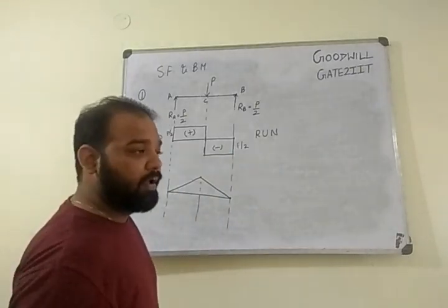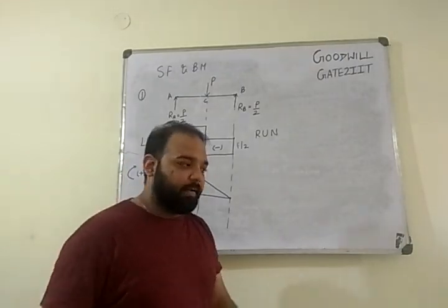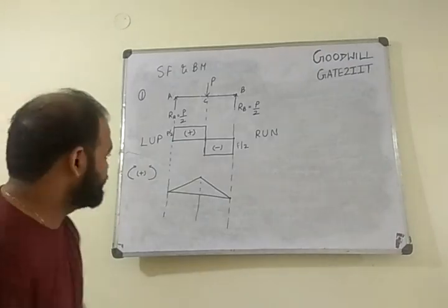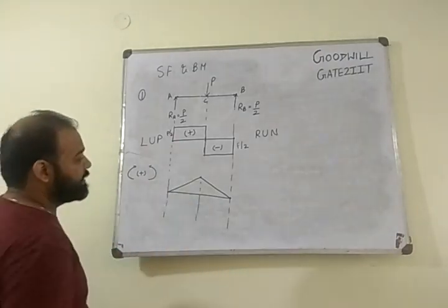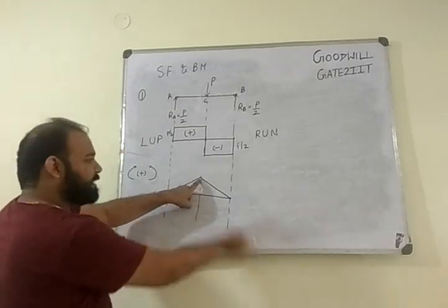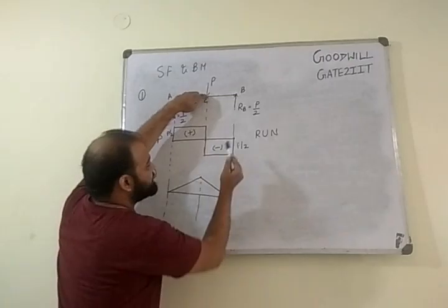So by straight lines, point loads. Any point load will create linear variations. P into X, P by 2 into X. All the X variations, X to the power 1, are nothing but linear variations. So you end up with this kind of diagram. Can anyone tell me what is the magnitude here? You either come from right or from left. Magnitude remains same.